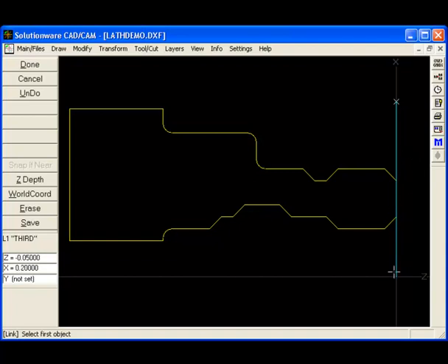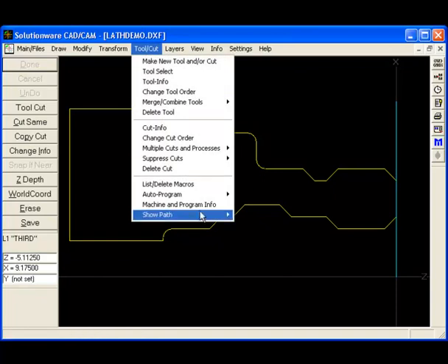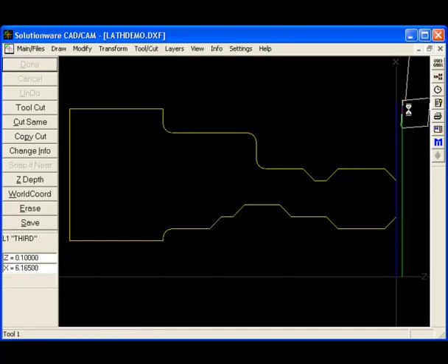Normally you don't have to worry about this, but again, we want to make sure we get a particular kind of Mazatrol process, an edge face, and we want to make sure the shape lines are going to be good, so we're going through this extra step. If you go to rerun the toolpath that you've got by going to Tool/Cut, Show Path at the bottom, and let's say All Tools, it'll now do a face rough that goes all the way down the front face. It might be going a little slow.